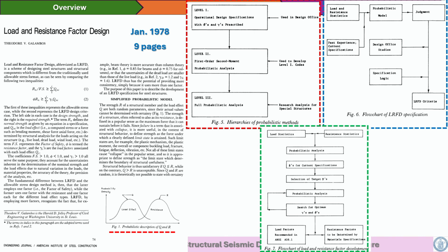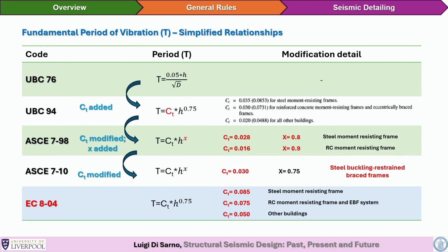So nothing new, but really a way to move from ASD, allowable stress design, to LRFD, that has been beneficial. And that has also brought us to more sustainable types of structures, because structures tend to behave these days lighter and lighter, more flexible. But flexibility should also be designed accordingly, for example, for non-structural components, like windows and all the building contents.